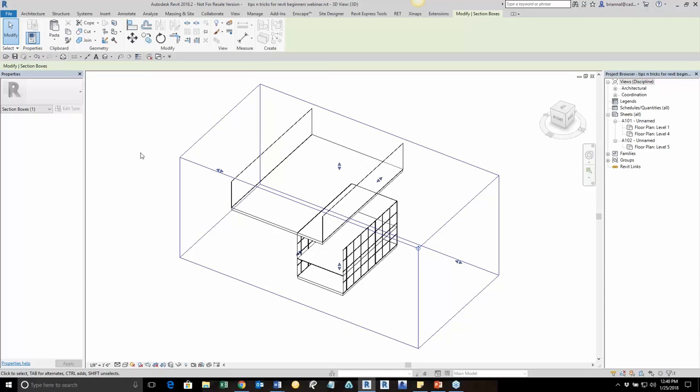And if and when making any sort of significant changes to a model, such as level or major geometry, it is recommended to make the changes when no one else is in the model. Another tip in regards to arrays, when you're using arrays for copying and associating things, after that array has been deployed within the project, ungrouping them can help, again, increase the model performance.